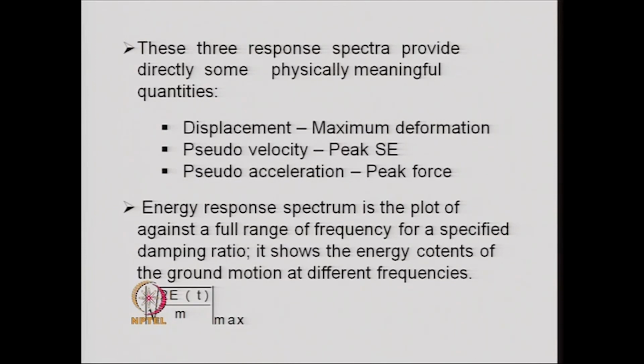These three response spectra provide directly some physically meaningful quantities. Namely, the displacement response spectrum provides the information about the maximum deformation that takes place in the single degree of freedom system. The pseudo velocity spectrum provides the peak value of strain energy in the system, and the pseudo acceleration spectrum provides the peak force in the system.